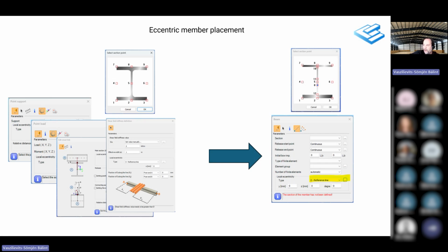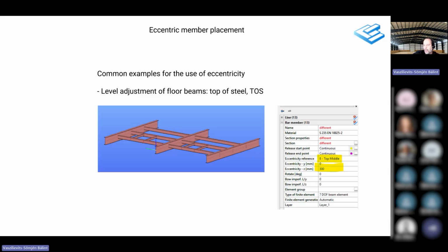And also what we added now, focusing on much more useful work for welded elements, is that new points have been added at the intersection of the web to the flanges and also a middle web position. Very often these are very practical and useful reference points when somebody works with welded sections forming an I section from 3 plates. I'll be showing very small examples of how it can be used.